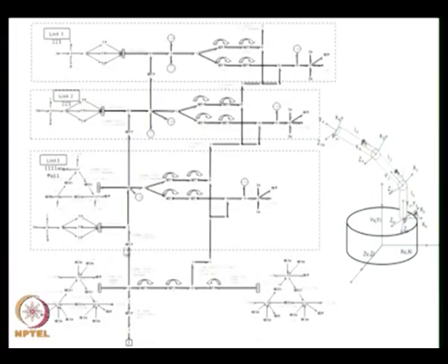This part represents the AUV or the underwater robot dynamics, shown here just for representation, and this shows its dynamics, or the bond graph model of its dynamics. This shows the three links of the manipulator. So this is the first link, second link and third link, and you can see the interactions between these links, as well as the robot and the manipulator and the AUV, shown like this here. So this represents the complete dynamics of the AUV and the manipulator using bond graph methods.